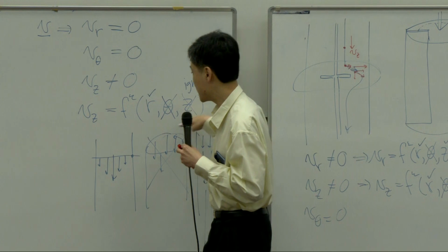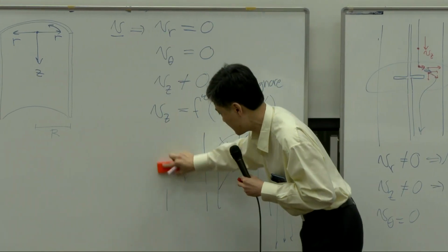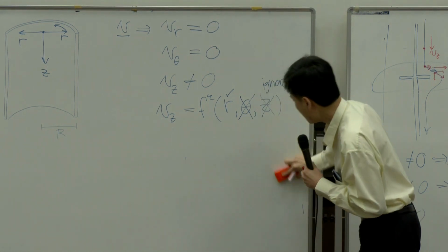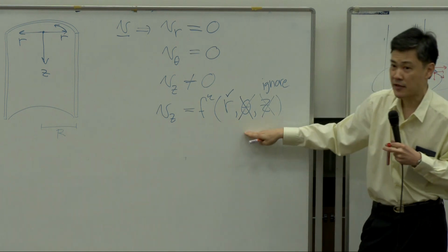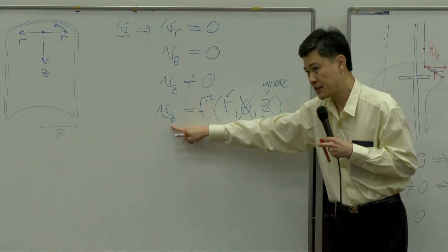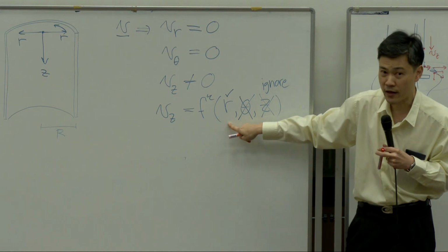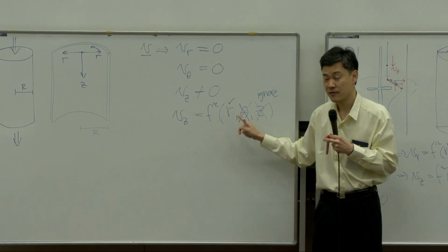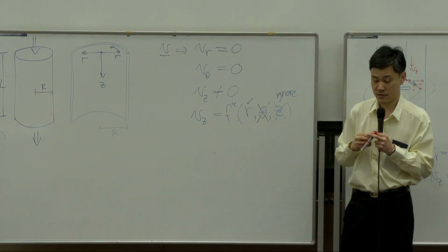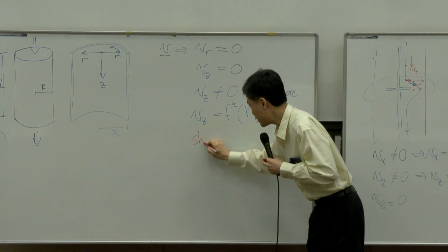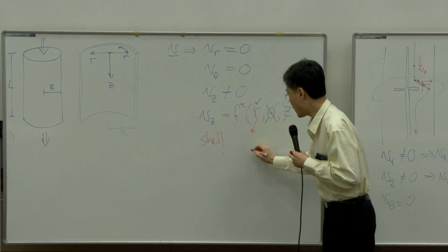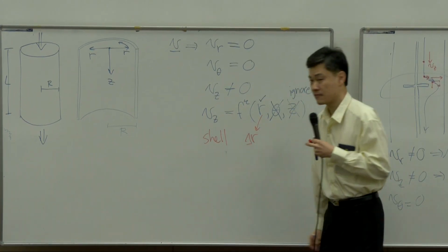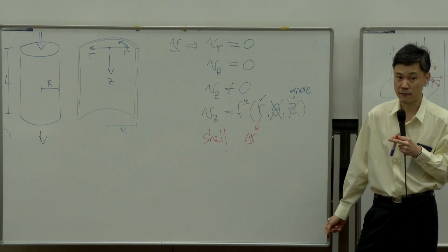All right? Because this function will define the shape of your shell. I told you that when you analyze velocity components and you found that Vz is a function of r only, that means the shell in r side will be thin. So for the shape of the shell in r, it is supposed to have a thickness of delta r, or thin in the r direction.